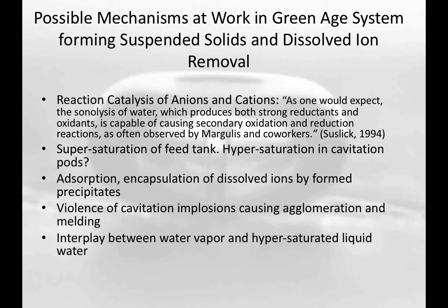You also will have absorption happening as you drop your iron out of solution. You're going to have these iron oxyhydroxides forming on your bags. They're very absorbent. The iron oxyhydroxide, especially when it's fresh and clean, will grab dissolved zinc right out of water. It'll grab other elements out of water. It'll glom it right out of there. So that's another potential action.